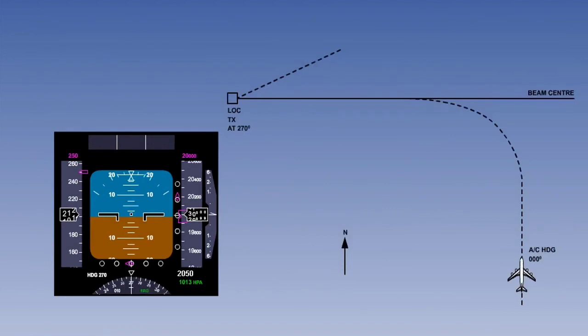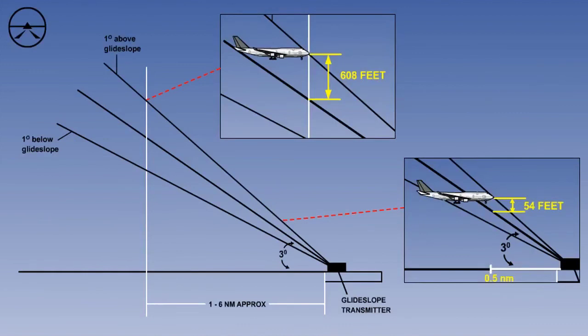The vital information to take away from today's lesson is that the flight director takes the raw information and provides either the pilots or the autopilot with computed information. This is derived from the rate of change of deviation and displayed as command bars on the primary flight display. During an approach, the flight director computed information must be modified as the approach progresses to reduce the commanded correction.